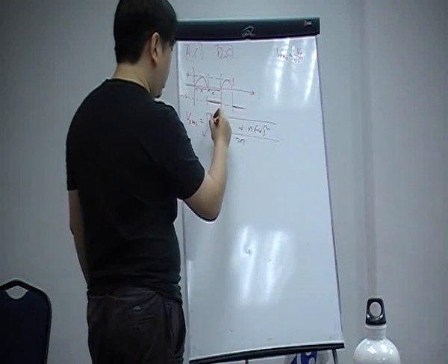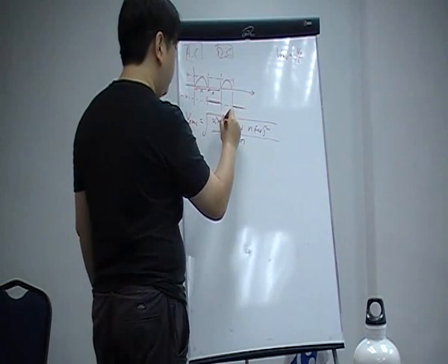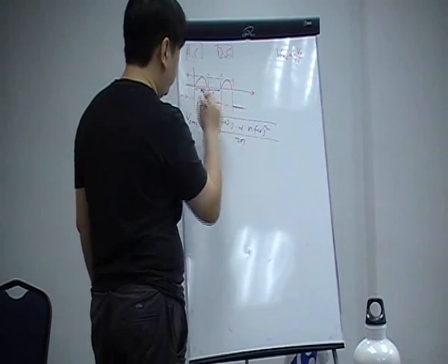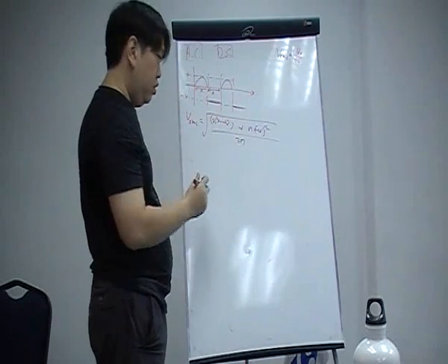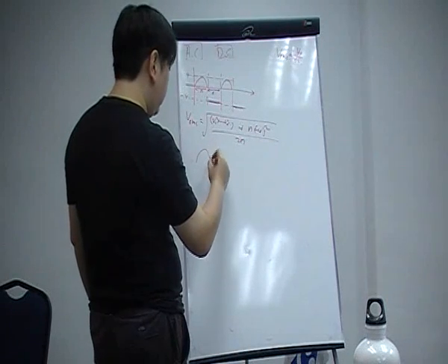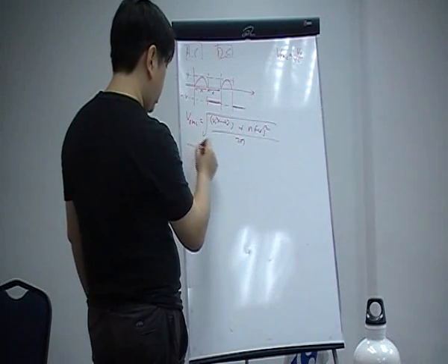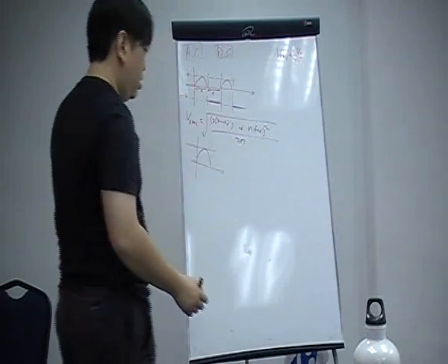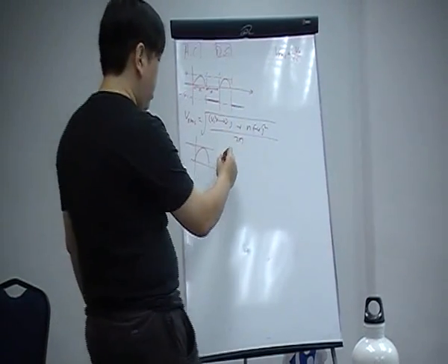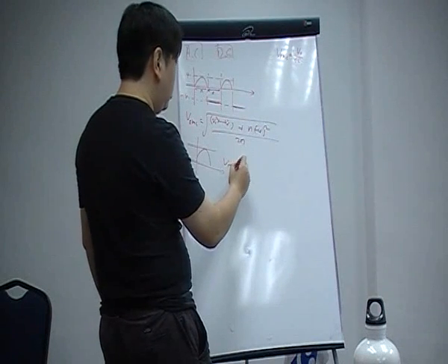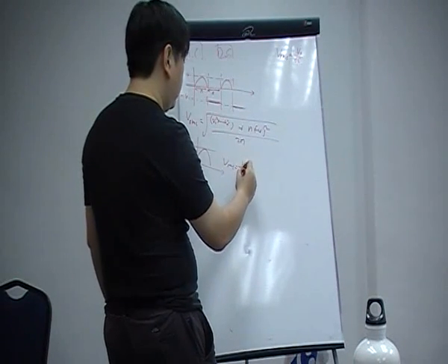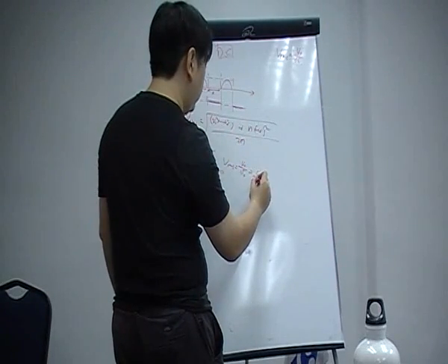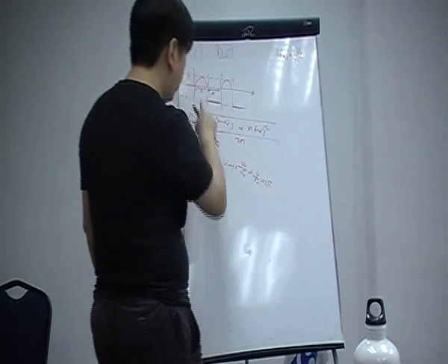So the idea is that I need V1 square, V2 square, until Vn square for the first arc. How do we do the arc? Take out the arc and reconsider it. Use the formula: at this arc, the RMS equals V naught over root 2, so 4 over root 2, which equals 2 root 2 for this arc only.